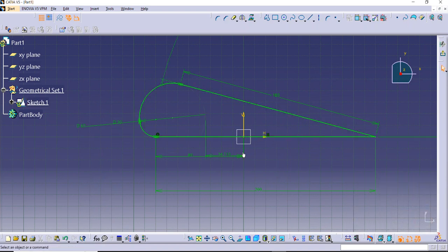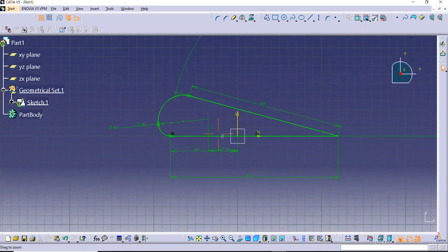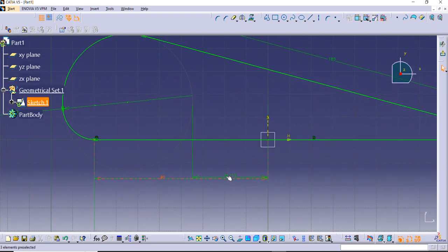So I'm going to click on OK, and here you will see that in one go everything is completely done. But here I have made it with respect to nothing else related to dimension, that's why I did it this way. If you are going to refer to some drawing, you need to avoid this auto constraint, because there you need to give the proper values, as at that point the value is very important.